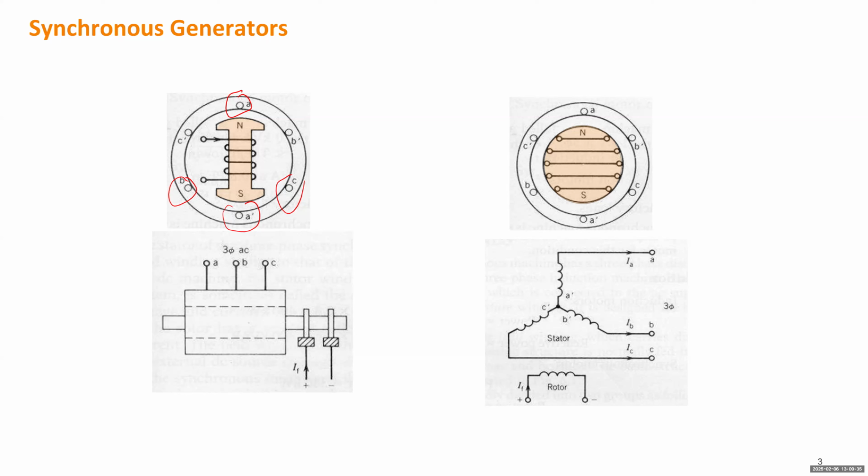But the rotor will be revolving inside of the stator, and it has a very small air gap, for instance, at this position between the N and A, but in the perpendicular direction, it will have a much larger air gap. Definitely, this is just a figure showing a very simplified layout of the generator. But if you are able to see real pictures of the inside of the rotor, you can still tell in which direction the air gap is bigger and which direction is smaller. So you can feel the change of the air gap due to the revolution of the rotor.